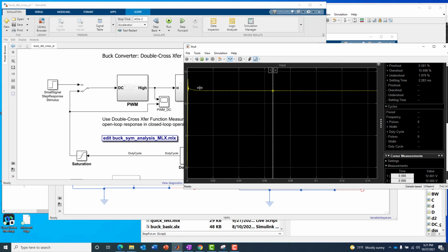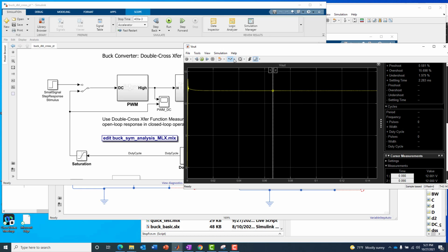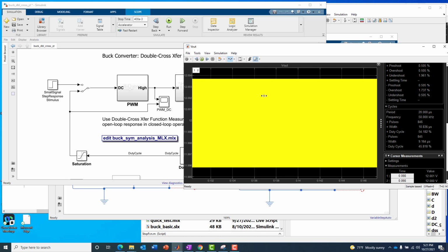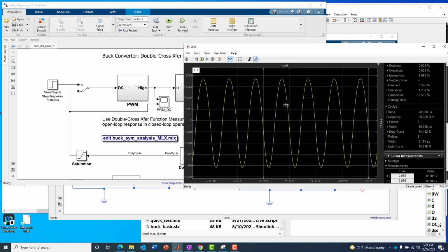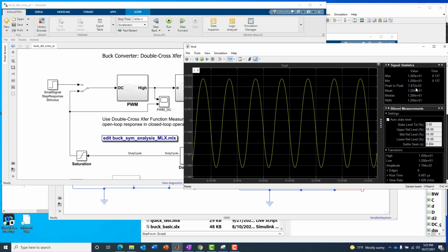And we can see again the transient response. And then we go to the end of the waveform near steady state. We'll just zoom in maybe around there, do an auto vertical zoom, and zoom more horizontal again. And we'll see we've got some variation, some ripple about our 12-volt set point, as is expected for any switching converter like a buck converter. And in this case, it looks like we've got about 7.88 millivolts or so peak-to-peak ripple around our 12-volt set point. So not too bad.